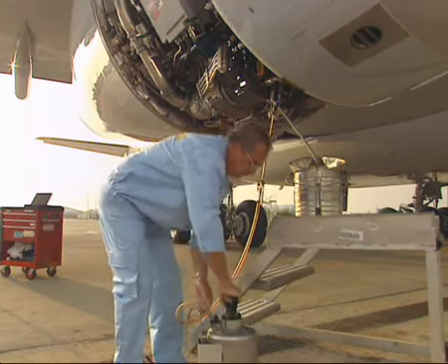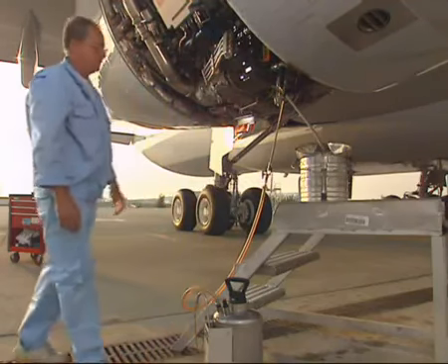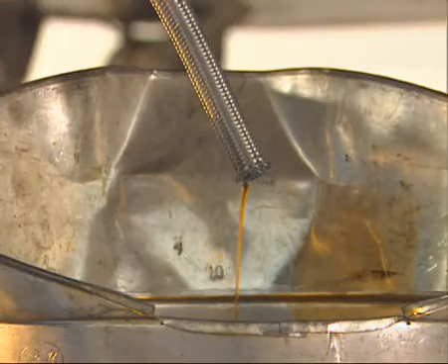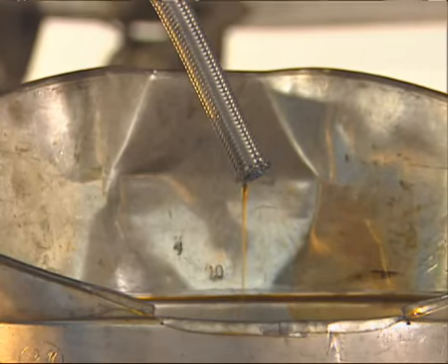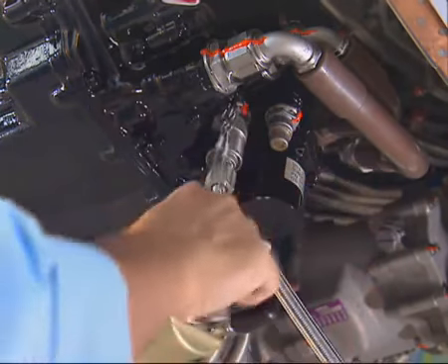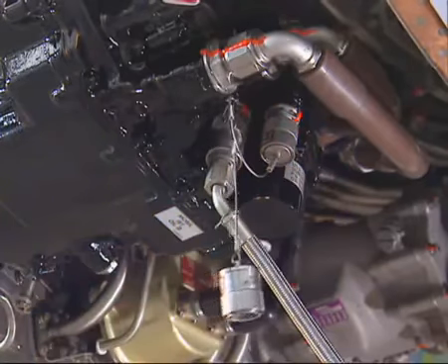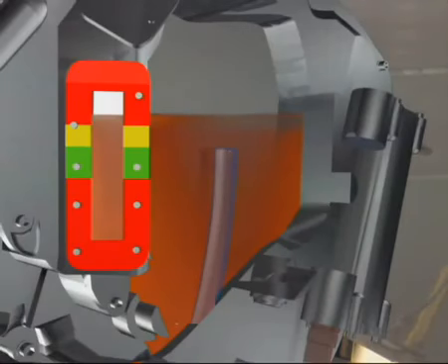Stop pumping when the quantity of oil collected at the overflow drain hose exceeds 1 liter or 1/4 of a US gallon. The oil will continue overflowing until the level has dropped down to the top of the overflow standpipe. While the oil is overflowing, remove the pressure fill hose. Install the dust cap on the pressure fill port. Once the oil level has reached the top of the overflow standpipe, the oil stabilizes at its optimum level at the top of the green band.